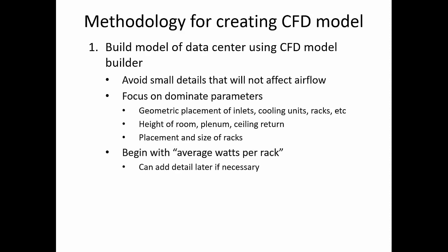So for creating a CFD model, we first build it in CoolSim. We avoid small details because they won't affect the overall outcome. You need to be careful not to over detail. It is not a CAD system, it's a modeling system. We're looking for big parameter variation, the most influential, dominant parameters, like placement of cooling units, racks and equipment in the room. Height of the room, we need the volume of the room of course, so plenum height, ceiling height, return height, placement of racks. Those are the important things.